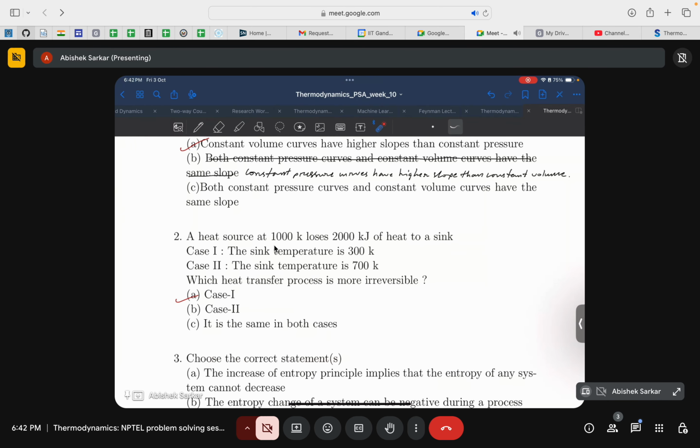If you recall, when we were discussing these irreversibilities, we mentioned a perfectly reversible heat transfer process. I mentioned that in a physical sense, this perfectly reversible heat transfer process is not possible, or it would be achieved only through a very long process, primarily because for heat transfer to occur, we need a temperature gradient. That is, there should be a temperature difference, but it is the presence of this temperature difference that causes irreversibilities to get imbibed into the systems.